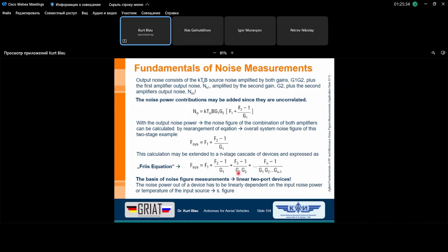because power amplification does not in every case mean that it's positive, that we have a cascade only of amplifiers. We can also have a cascade of an amplifier, then for instance a filter. A filter is a passive device, and the filter does not have an amplification larger than 1. It has an amplification, in brackets, of lower than 1. It has a so-called insertion loss. It has a loss. It's a passive device, and a passive device has losses.